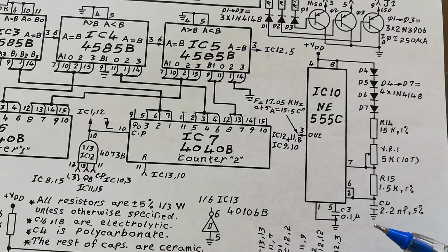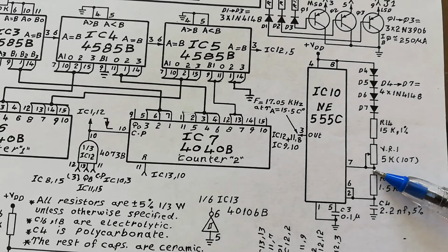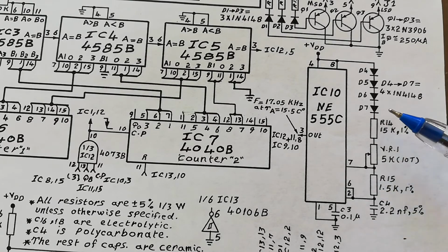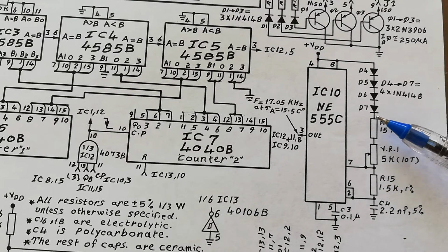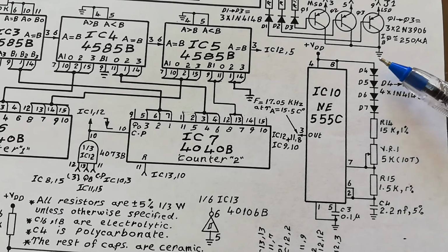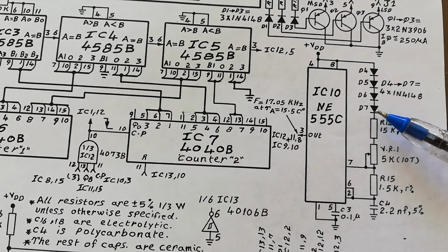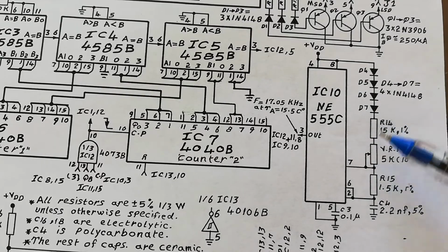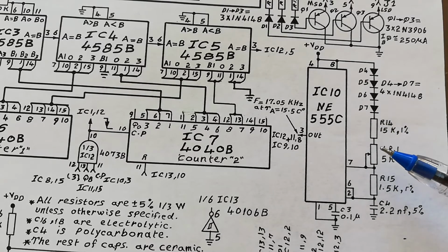And to calculate the time inside the chip itself, you have to go to the charging and discharging of caps, with a voltage that starts from 1/3 and goes up to something less than 2/3, because, like I said, you have about 3 volts deducted out of the VCC. So you have to use a special formula to get something near this. Anyway, this thing works, and it works just fine.